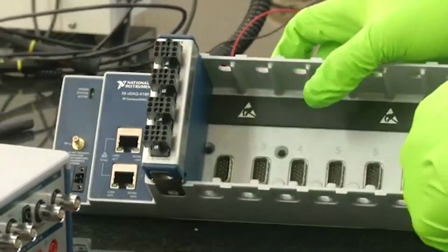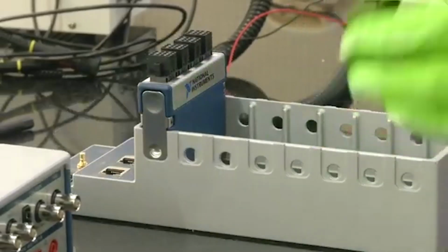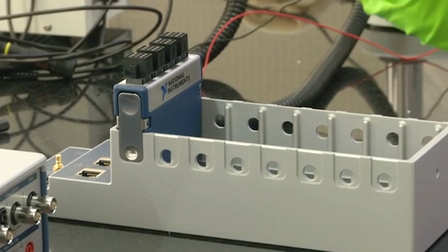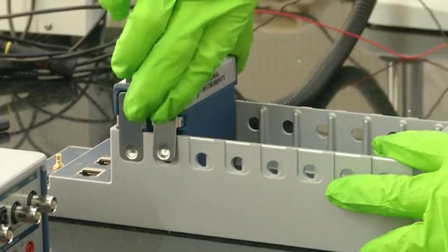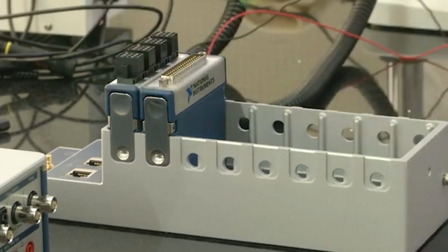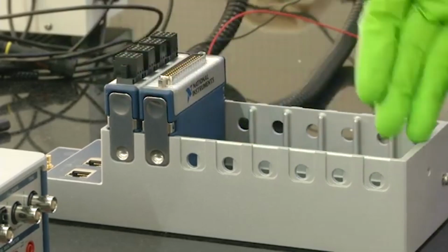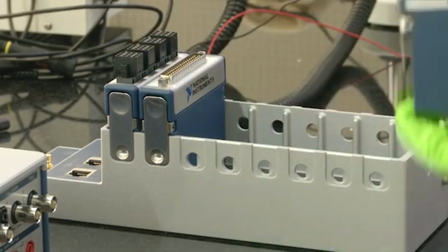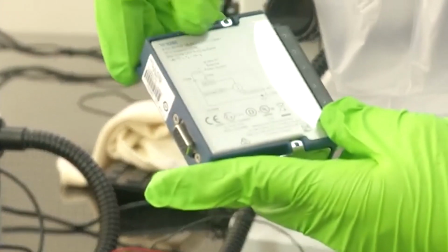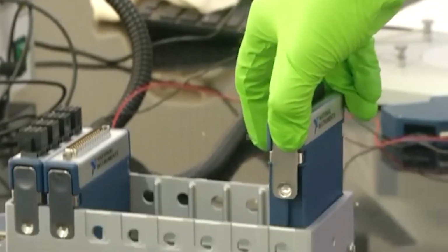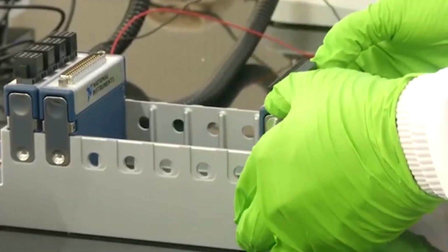If you look at the chassis, it contains a number of channels. Simply select the required signal conditioning unit, or as they call it, a module, and place it on the appropriate channel. The advantage is that it can be interchanged. It need not be fixed only to that particular channel; it can even be fixed to the last channel, anywhere it is required. We also have analog output, which can produce up to 20 milliamps of current, and it is a 16-bit analog output too. You can use this in the same chassis itself, and all units can be operated at the same time.